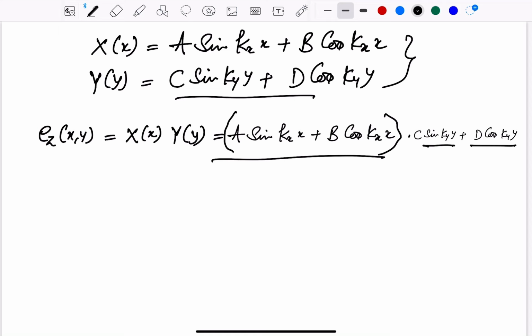Fine. And similarly you can write down the overall field just by multiplying e to the power j beta z. Fine. So once you have this Ez component, we know how to write the other components. I'm talking about the Ex, Ey, Hx and Hy. These are the transverse components, in the direction of the propagation. So we saw in our previous classes how we related this Ez component with the different Ex, Ey and Hx components. Okay, so hopefully you can recall those things.